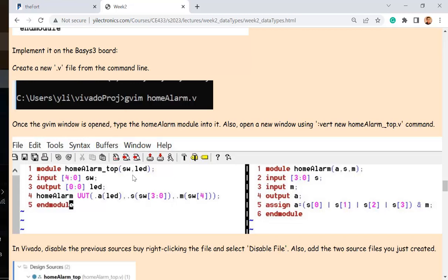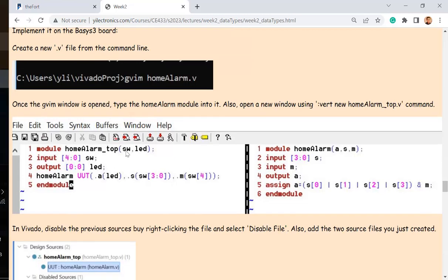So you load that constraint file to Vivado, and then it's going to recognize that SW is a switch. I didn't put a length in the front, or prefix in the front. So by default, it's going to be a 16-bit switch. So SW has 16 bits in there. That's what you already defined in the constraint file. Same to the LED. If you look at the board, there are 16 little tiny surface mount LEDs on the top of each switch. So this is 16-bit as well.